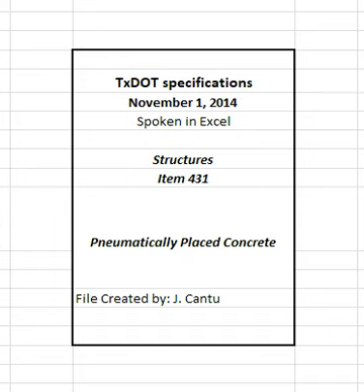Support reinforcing wire fabric or bars using mushroom-headed anchors, expansion hook bolts, or grouted rebar capable of resisting a pull-out force of 2,500 pounds. Space anchors no more than 12 inches center to center on overhead surfaces, 18 inches center to center on vertical surfaces, and 36 inches center to center on top horizontal surfaces. Use at least 3 anchors in each individual patch area.